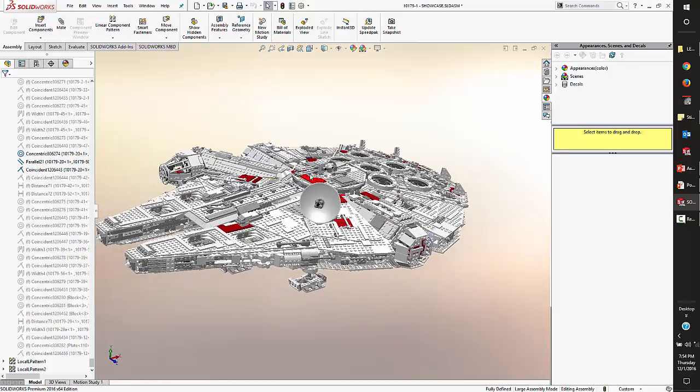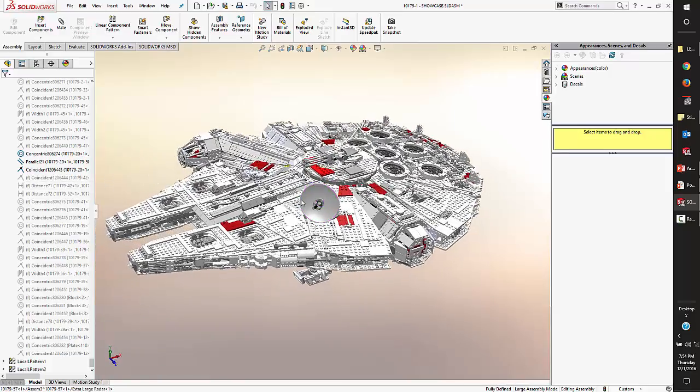So really what it comes down to is there's a little bit of onus on me. If I make a change to a component, I am going to have to take time to go to my assembly and manually update it, as opposed to letting SolidWorks update it. So here's how it works out. I can take 5 minutes and put that extra bit of work into it because I know where to go and what to float. You have to right click on the part, float the part, let the mates reevaluate, and then right click and fix the part. That's really the whole thing that you have to do.